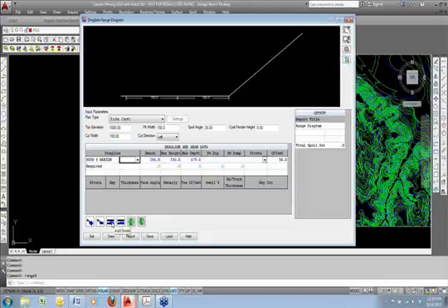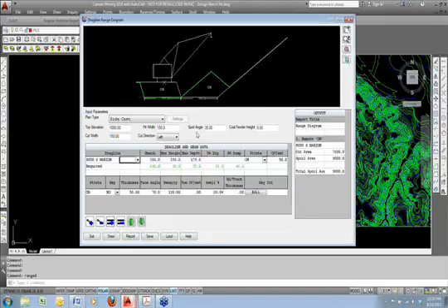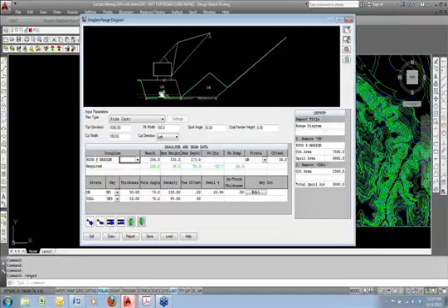So I'll just hit the first Add Strata button. And it instantly added a default thickness of 50. It called it overburden. And so we'll add the next strata below there. Coal, let's say it's about 8 feet thick. You can change your angles. So my overburden should be right around 65 degrees. I want my coal to be 85 degrees.